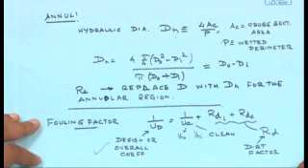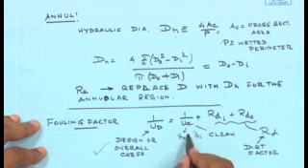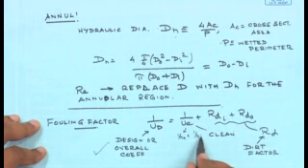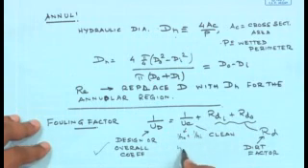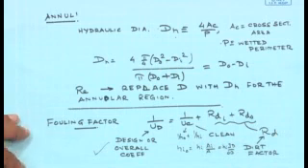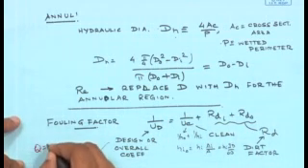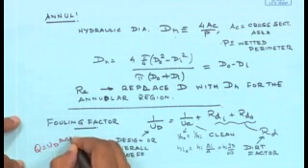And one more thing that we need to keep in mind is that the clean overall coefficient is simply 1 by HO plus 1 by HI, and the heat transfer coefficient on the outside, directly from geometry, is HI times ID by OD. And finally, once you get all these, you are going to get Q is equal to UD A delta T.